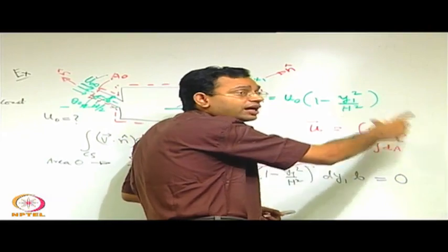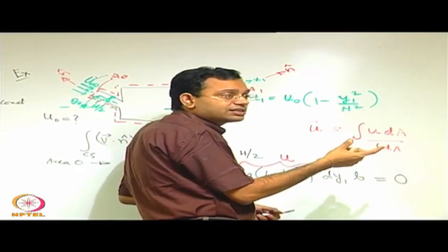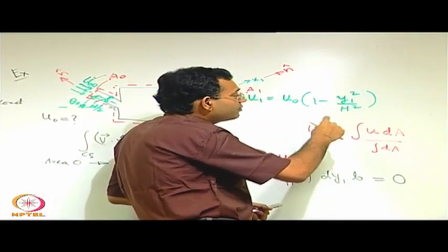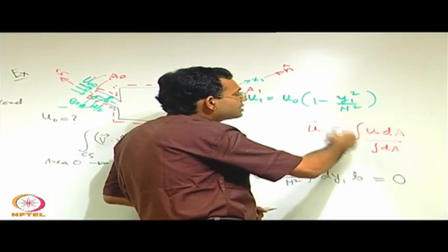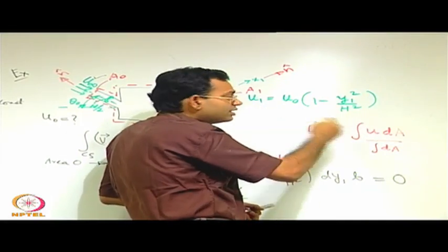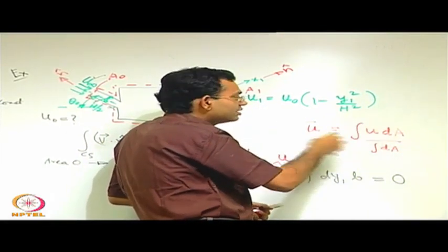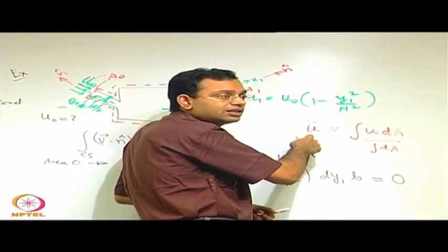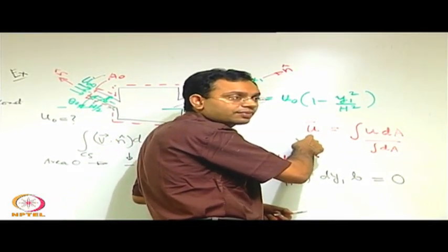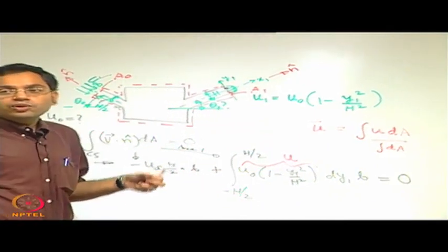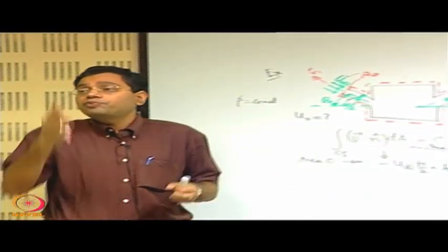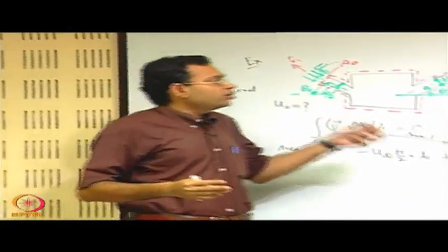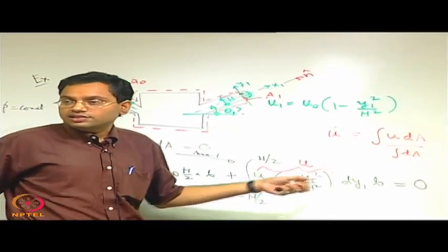So, if the velocity profile was uniform in a hypothetical case, but the flow rate still the same as in the real case, then if you equate those two flow rates, that equivalent hypothetical uniform velocity is called the average velocity. So, it is like an equivalent uniform velocity that would have prevailed across the section, satisfying the same volume flow rate as in the real case.